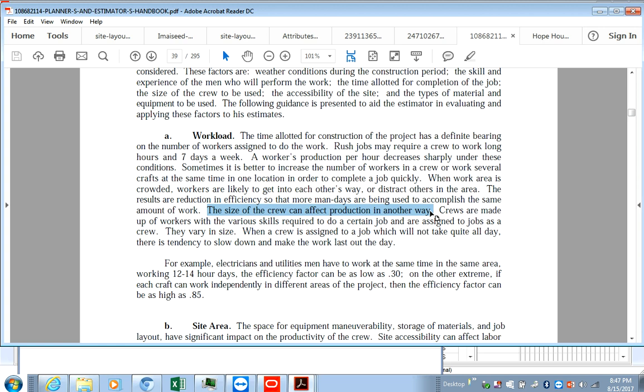But health and safety will probably say that we don't want to lift 70 tons, we want to lift 50 tons, just in case. So that increases the length of time it will take the crane to lift things. If we're lifting a lot of heavy material, we'd have to put it in batches of 40 or 50 tons per lift, maximum.